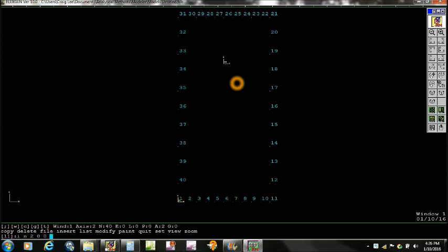We're now going to set that axis system active, and now we're going to insert a node with a radius of 2 inches, and we're going to copy that node 35 times. Go around the circle with a 10-degree increment, and those are those nodes there. That forms our first circle, and we'll confirm creation of that.